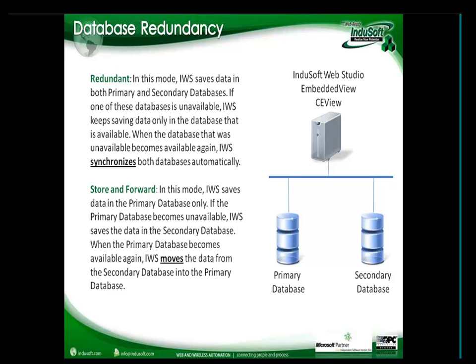In InduSoft, you have the ability to save and retrieve data from any SQL relational database. Could be Microsoft SQL Server, Oracle, Sybase, MySQL, simple Microsoft Access files, any database that you can connect to using ODBC, OLEDB, ADO, or ADO.NET. And the nice thing is InduSoft provides a user-friendly interface to configure the link with the databases, so you do not have to know SQL or write complex code scripts to connect to the databases.